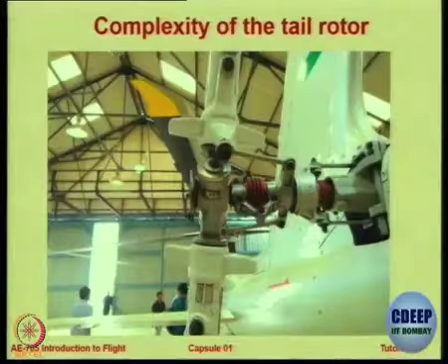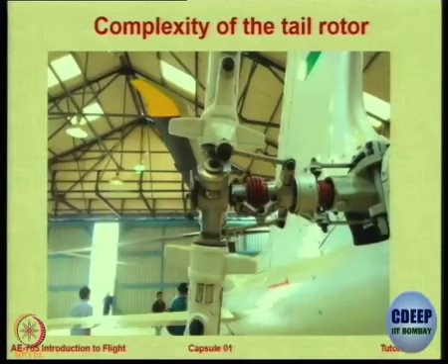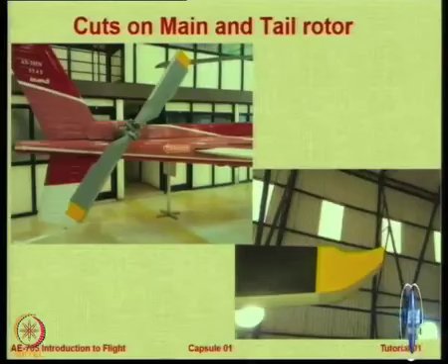So you put a rotor on the back, give a force to counter that. The moment created by the tail rotor is just enough to overcome it, unless you want to intentionally move to the left or right. Okay. So that's why the RPM of the main rotor and the tail rotor have to be coupled, because as you increase the lift or the RPM, you have to also have a corresponding change. So it is complicated, and this is the most common reason for mechanical faults in helicopters. It's a nightmare for maintenance. So we will see how people have attempted to modify this.